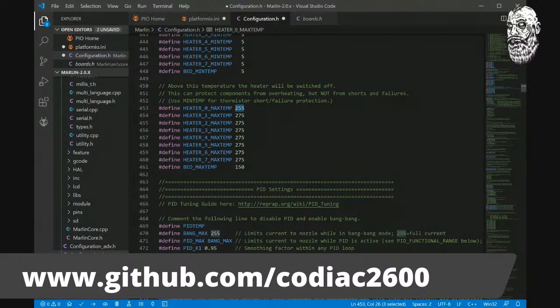So you still should not be printing with Capricorn tubing at 280, 290 degrees Celsius. This is why people switch to an all-metal hot end, because an all-metal hot end is only limited by the max temperature the actual metal material can last. On a stock E3D V6 with an aluminum heat block, your max actual printing temperature is just below 280 degrees Celsius. And that's another marketing issue.